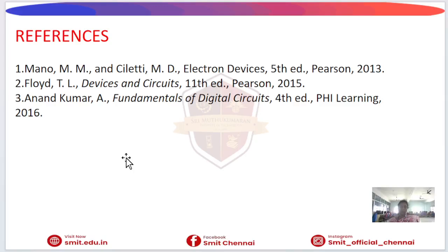So in today's topic, we studied what MOSFET stands for and the important points of the MOSFET. That is, it is a four-terminal device including the body. We discussed the four terminals, and that the MOSFET is a voltage control device having high input impedance, fast switching speed, low power consumption, and it is a unipolar device. And the applications we have also seen. These are the topics covered under the MOSFET, and these are the references.